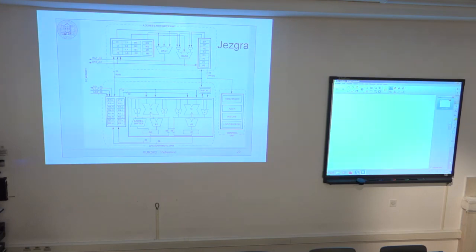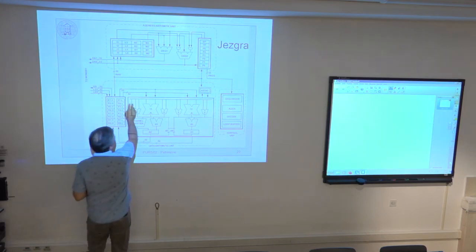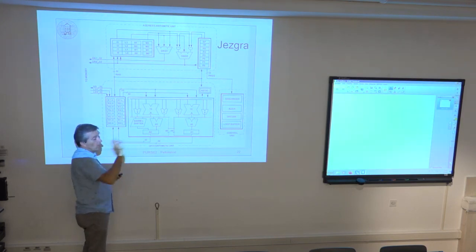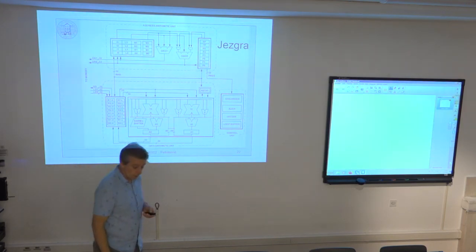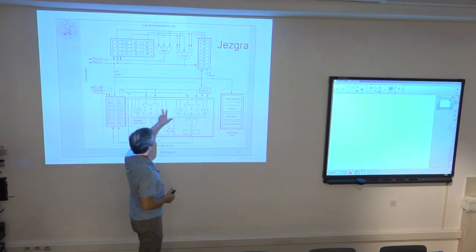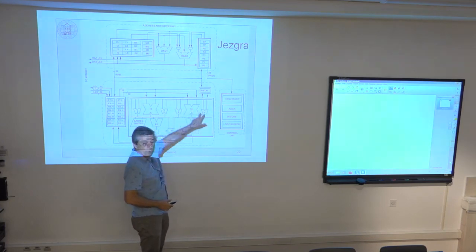So altogether I have these 64 bits, and these 64 bits can be treated as one vector of 4 times 8 bits and another vector of 4 times 8 bits. In this case, I would add the first 8 bits of the first vector to the second vector, and I get the 8-bit result for the first entry of these two vectors. Then the same thing for the second entry of the input vectors, the third entry, the fourth entry.